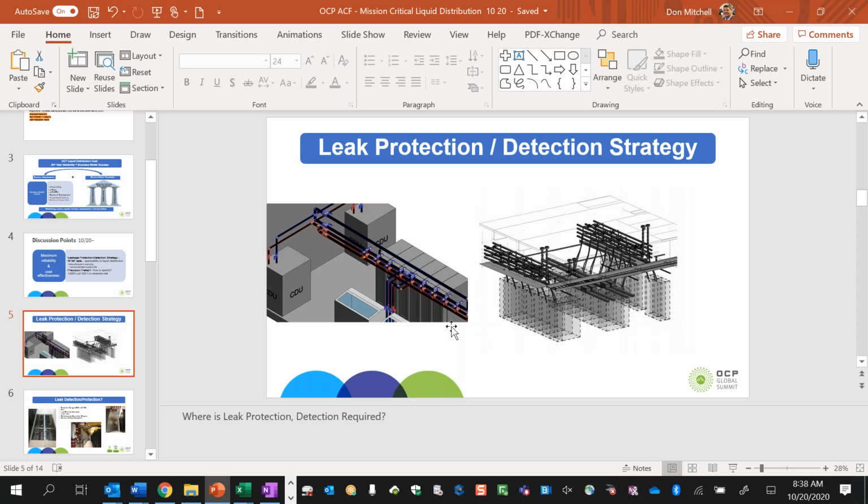Okay. Now, if you had a solid piece of pipe going through your data center from one point to another, just one solid segment of pipe, would you feel a need to put leak detection and protection on that? I would weigh it against my dew point in the data hall and the water temperature in the pipe, but in general, no. We looked at human error with all the valves as our highest risk of a possible leak, and that's why we protected it here with all of our valves and our connection points. Makes a lot of sense.